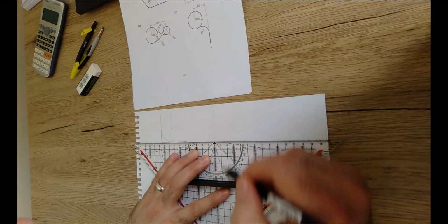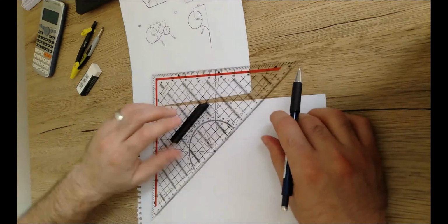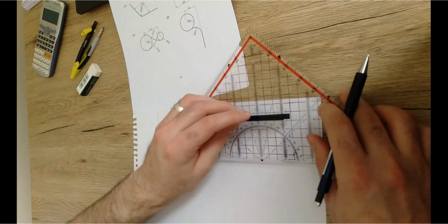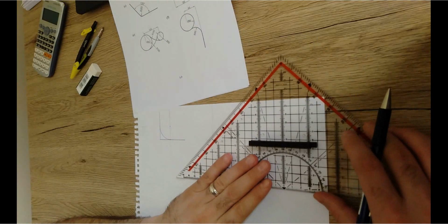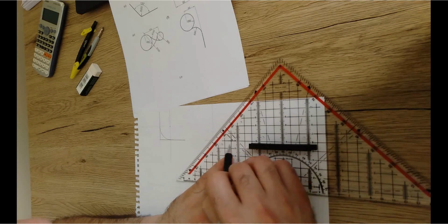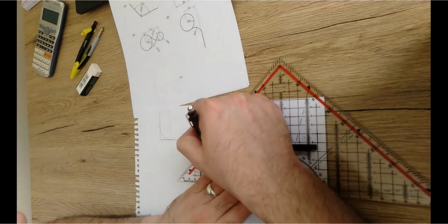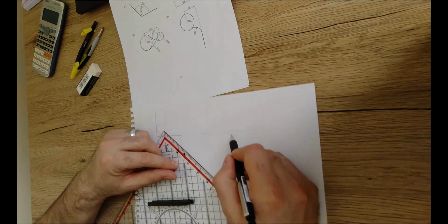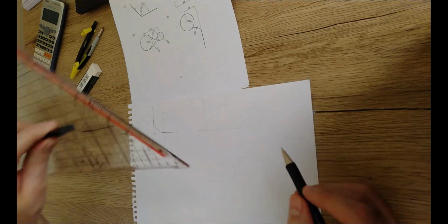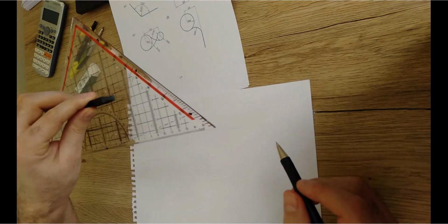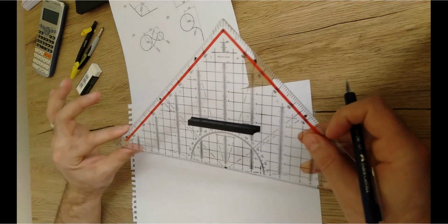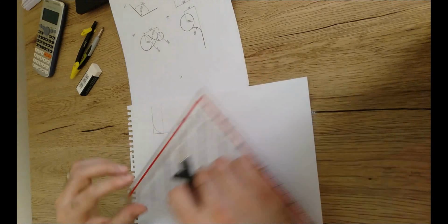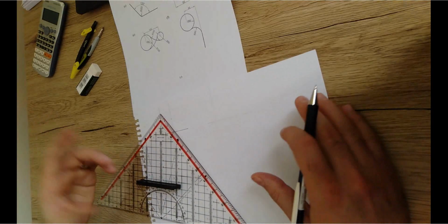So I'm gonna extend this line here a little bit, then from any point like this point, I'm just gonna align this black line over this horizontal line, then I'm just gonna draw a line. The angle between these two lines is definitely 45 degrees because the triangle that I used was the 45-degree triangle. It means that this angle is already 45 degrees. So I set up here over a line, then I draw a line. So definitely this line over the horizontal axis will be 45 degrees.